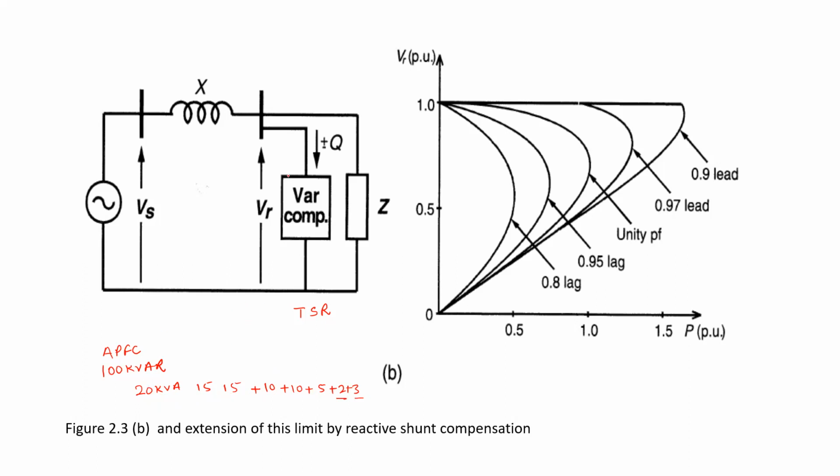So the shunt compensation, which is connected to the load side, the best example is the APFC. And if you are maintaining the APFC properly, by a proper division of the number of capacitors that can be switched, and this capacitor switching may be by, say, a contactor, but it is controlled by the thyristor.